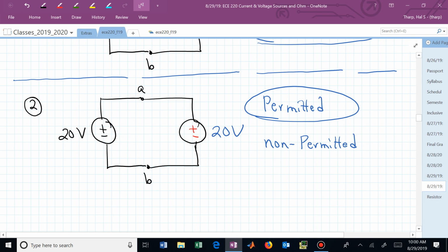The question was, this is just for ideal. Yes, it's just for ideal, but most of this class, we're assuming ideal conditions. In the lab, you're going to have practical scenarios, so your sources may not just be a pure voltage supply. You may say, oh, there's some internal impedance, so you model that as a resistor. But when we start modeling, we're assuming this is the ideal behavior of our source.